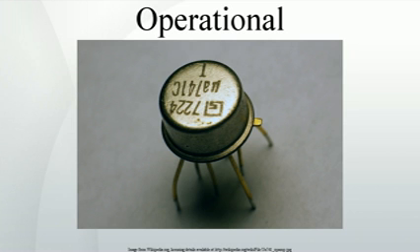High input impedance at the input terminals and low output impedance at the output terminal(s) are particularly useful features of an op-amp. In the non-inverting amplifier on the right, the presence of negative feedback via the voltage divider Rf, Rg determines the closed-loop gain ACL equals Vout/Vin. Equilibrium will be established when Vout is just sufficient to reach around and pull the inverting input to the same voltage as Vin. The voltage gain of the entire circuit is thus 1 + Rf/Rg.